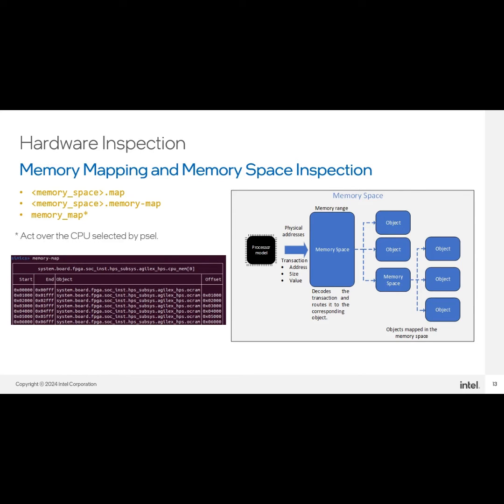As part of the output of this command, the memory space to which each device belongs is presented in the space column in the table. A useful command is memorymap. This displays the physical memory map including translator for the current selected processor. Information from another processor can be shown using the object command parameter.